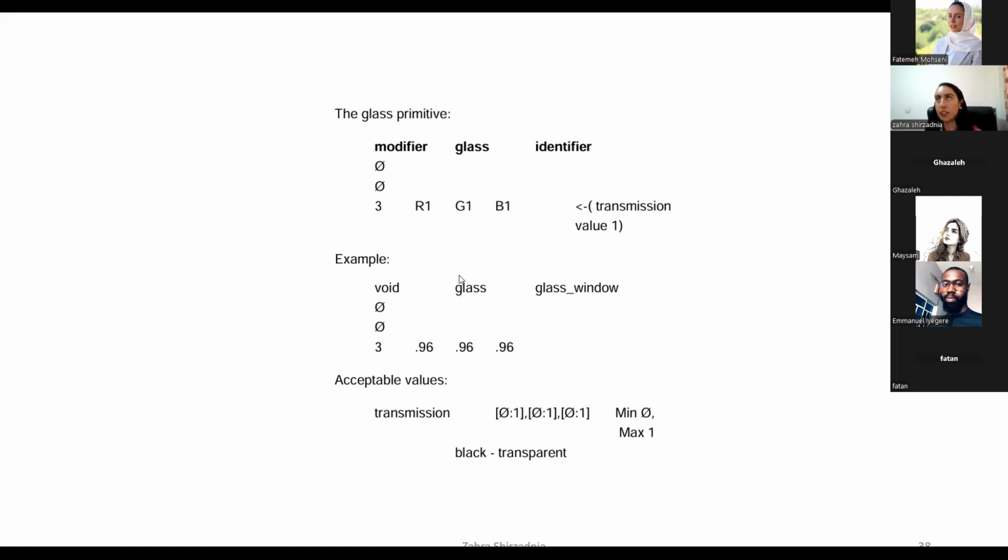But you can actually customize based on the type of your visible light windows. You can customize it and change the value of it. For example, as you see in the canvas, I use 0.68 for visible light, and for the transmission.